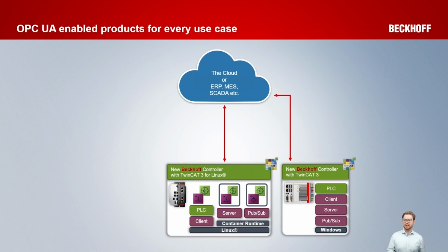But it could also be a new Beckhoff controller that runs TwinCAT 3 for Linux, with Linux as the base operating system. On here, you could have the PLC and client running natively on Linux and have the TwinCAT OPC UA server or the OPC UA PubSub functionality running in containers on top of a container runtime.